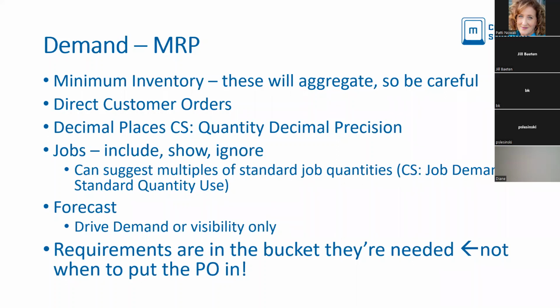So for example, if you have 2 hours of setup time, or 120 minutes, for a job that you normally expect to make 1,200 pieces, your company expects that you'll invest those 2 hours and get 1,200 pieces out. And that adds about 6 seconds of setup time per part produced. So that's 120 minutes divided by 1,200 parts, a tenth of a minute. So that's 120 minutes peanut buttered over those part numbers.